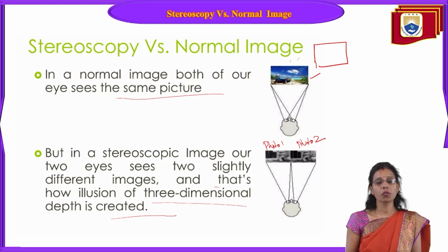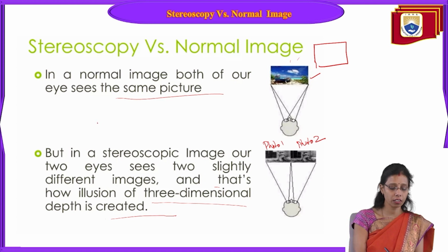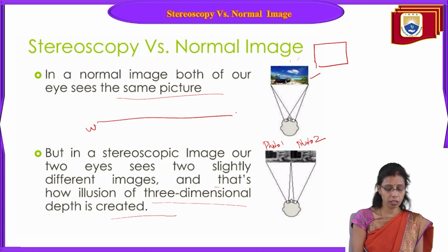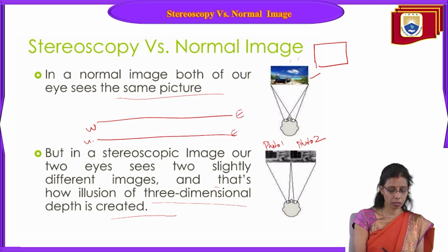If you are going to take photo number 2, we have to take photo number 3. If you are going to take photo number 4, either you take photo number 3 or photo number 5. Then only are we able to see the stereo vision. Otherwise, we are unable to see the stereoscopic vision. So it should be from the same series, the same flight line direction. The flight line direction should be either west to east or east to west. Okay.